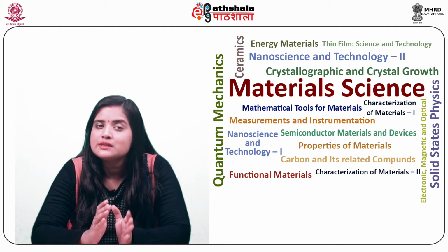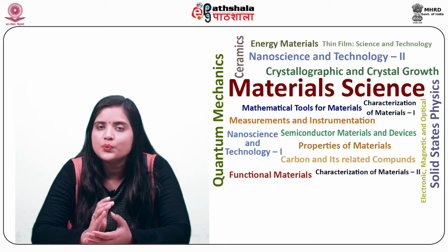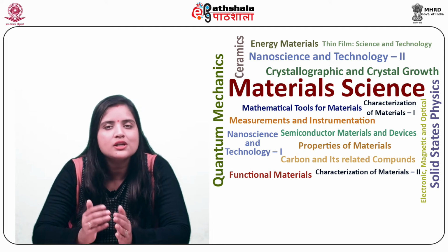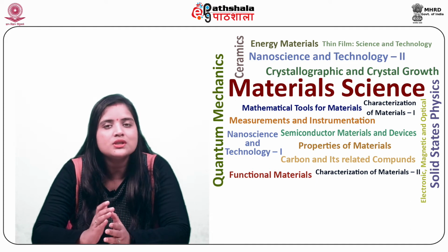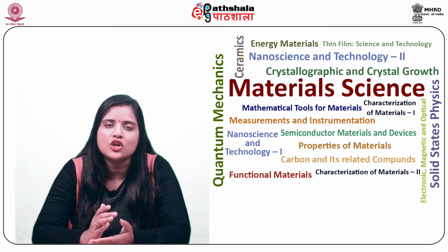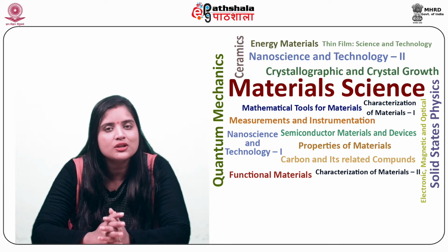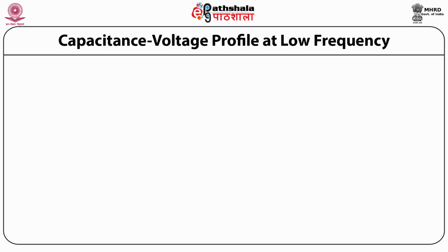voltage. Some non-ideal effects such as interface traps and oxide charges have an impact on the small signal range as they influence the velocity of admittance change of the metal oxide semiconductor capacitor with gate bias. We will next study the capacitance voltage profile at low frequency.